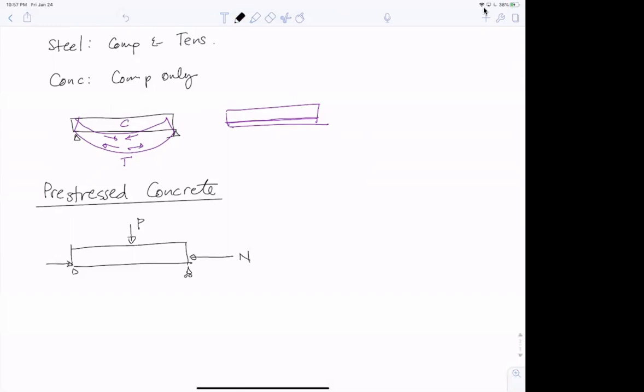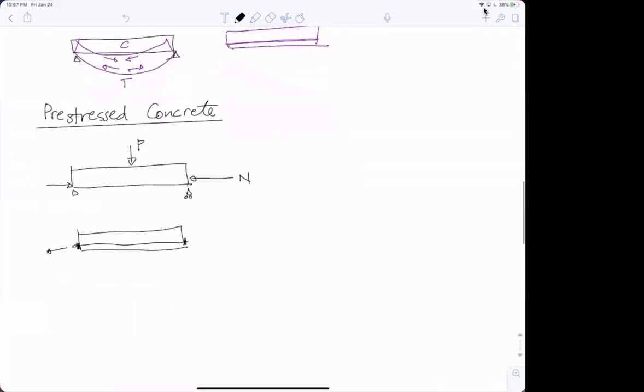And so how do you do that in a pre-stressed concrete beam? What you can do, one way, is you thread a bar through here. You pull a bar, and then you lock it down with a nut. And so it's like a giant rubber band in the bottom of the beam. So this beam, when you put that load in there, is now gonna want to arch up because you've put stress in the bottom.